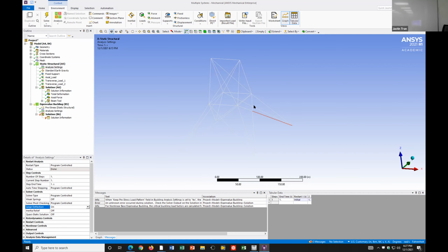But in order to actually get numbers that you can trust, you actually have to apply an oscillating mode like this. And that's what the harmonic response is. A few people have asked me about harmonic responses, so I'm going to put together a handout for next week. But these are just the shapes, so you don't take these numbers seriously. These numbers are only there to show you this is going to deform more than this one, but it's not a true deformation until you actually apply it.